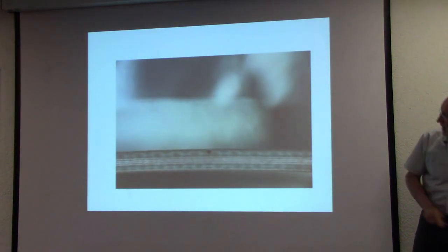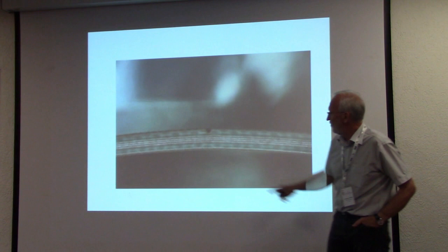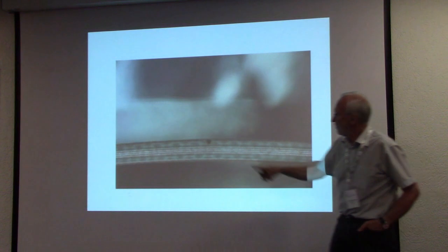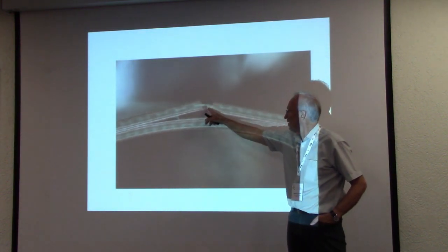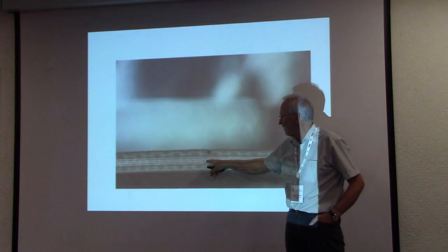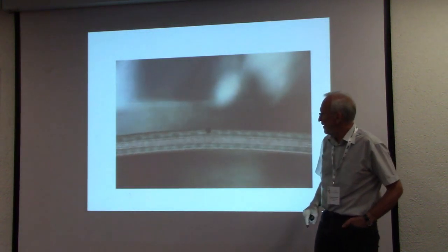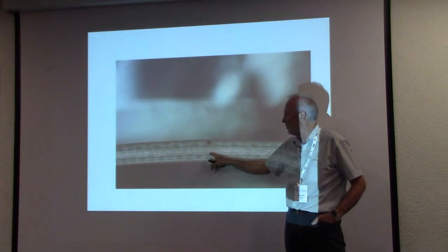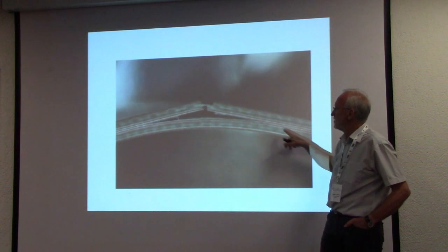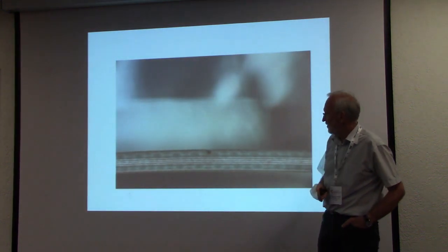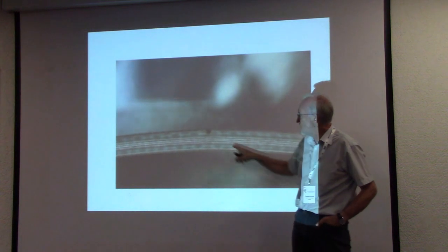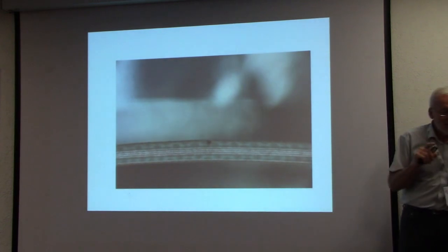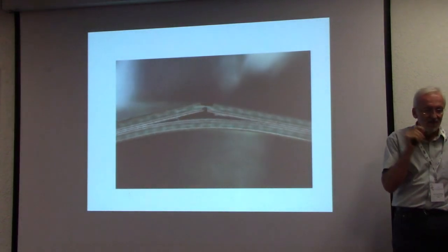Or here you can see another experiment where we have measured, for example, the interface strength simply by a macro test of, well, you have a crack running, and if the interface strength or the interface toughness is significantly smaller than the toughness of the material, then you always get this deflection, and then you can simply calculate the fracture resistance or the delamination fracture toughness of this material, as long as it is a really